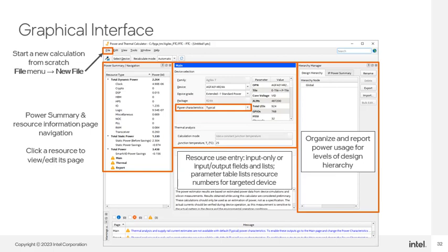On each page, discussed in detail later, specify logic resource usage, including ALMs and flip-flops, RAM and DSP blocks, clock domain properties and used PLLs, I/O and I/O-related IP cores, and transceiver block use and configuration. You can also specify CPU core usage when using a device variant that includes the hard processor system. Other pages may be available depending on the target device selected.